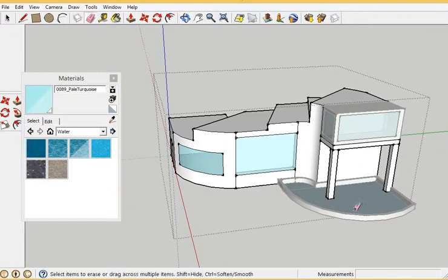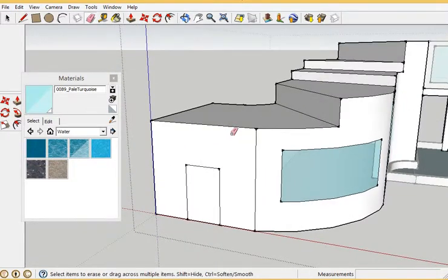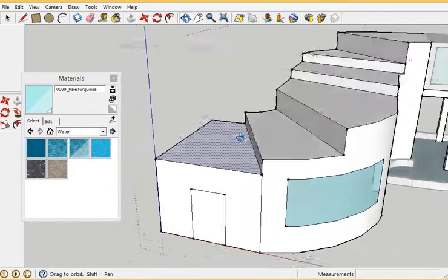If I wanted to have that rotate back, I could just click here, apply, and then, again, hit apply. So, as you can see, we have a lot of different options, and we can constrain people to making their rotation very specific with the rotate tool.